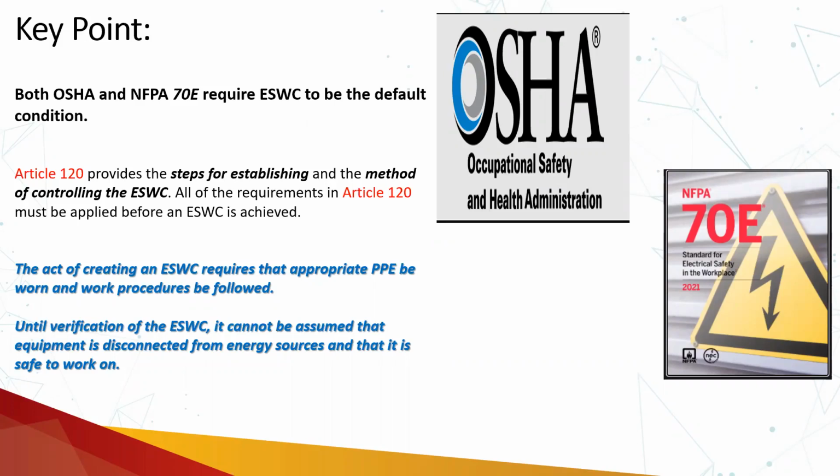So this residual charge, what do we call this? Okay. If there is a residual charge, we need to discharge those circuits. Maybe the cable is put off, but there will be residual charge remaining in those cables. So either we should wait for a period of time in which that charge dissipates itself, or if not, then we have to forcefully ground and short that so that the charge is dissipated.